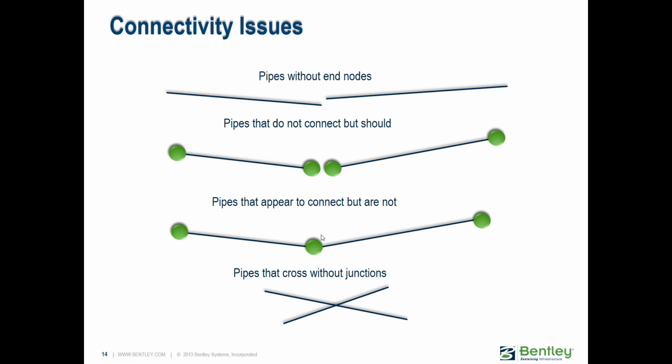So when you're bringing in data through ModelBuilder, especially geospatial information and DXF files, it's really good to go in and do a thorough check to make sure that data was imported correctly, and to clean it up a bit. And we do have quite a few different tools. There's a tool called Network Navigator included in Hammer, and that has a lot of different queries that can help you identify things in the model that may not be right, and things that may need to be cleaned up.